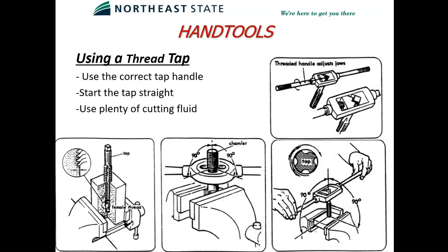When I say chips, if you've ever drilled a hole with a drill bit, and you have the shavings come out, and maybe a long spiral shaving, well, the taps are making that shaving as well. But you don't want that in a tap. You want to break that off in small little pieces and have those little pieces come out the flutes of the tap, those little grooves on the side.